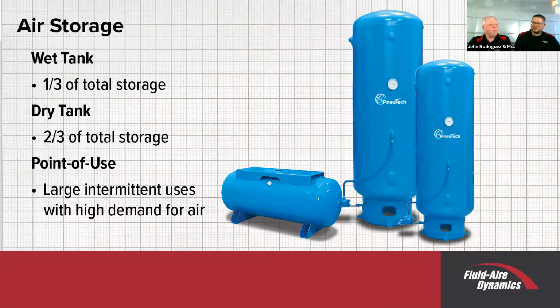Remember, 70% of that moisture comes out of the air compressor. If you don't drain it, it's going to end up someplace, and you'd rather have it in a wet tank than downstream in the dryer. So that's part of the reason for the wet tank. Obviously the dry tank is something we'll talk about later in another segment, to give you some information on the best sizing for a given system. But again, contact us. We can help you through the sizing of tanks.